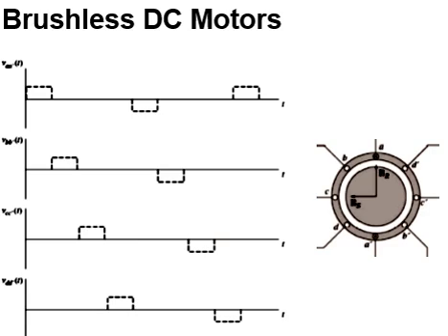So it can easily be implemented in applications where small motors are used, or applications where changing the motors or changing the brushes is quite difficult after some time. So in those applications it is desirable to use brushless DC motors.